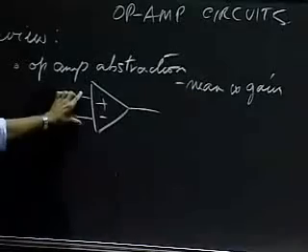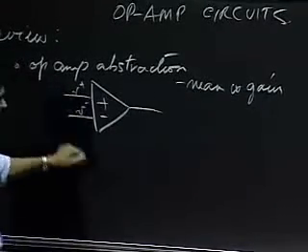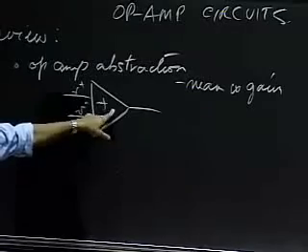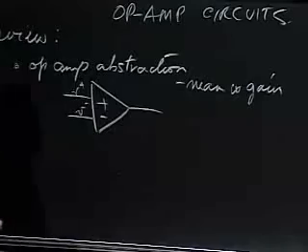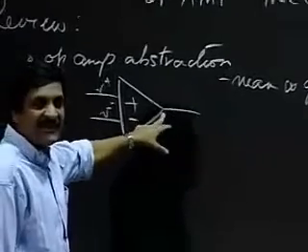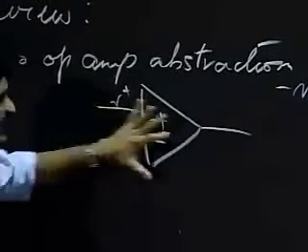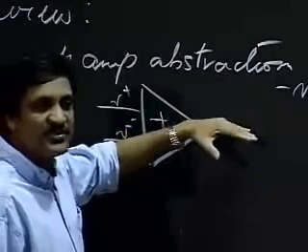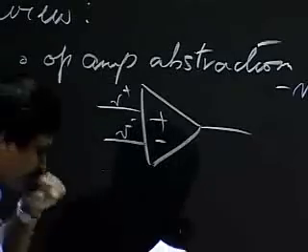So if I had a small voltage difference here, so I call this V plus and this V minus with respect to ground, then this gain here would multiply the difference by a large number, thereby giving me an output that was on the order of 1,000,000 times greater than this difference. And because of that, when I use the op-amp in a mode like this, without any negative feedback, the output would usually thunk up to the positive rail or the negative rail.